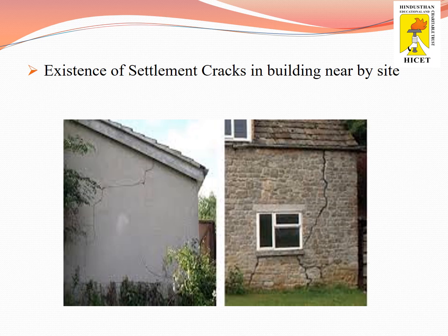Evidence of cracks in the site or a structure. From that, we can come to a conclusion that the soil is vulnerable to settlement and may cause heavy damage to the structure while we are imposing heavy load on that particular site. So by visiting the site we can observe these types of cracks, and then we should be more cautious in that particular area.